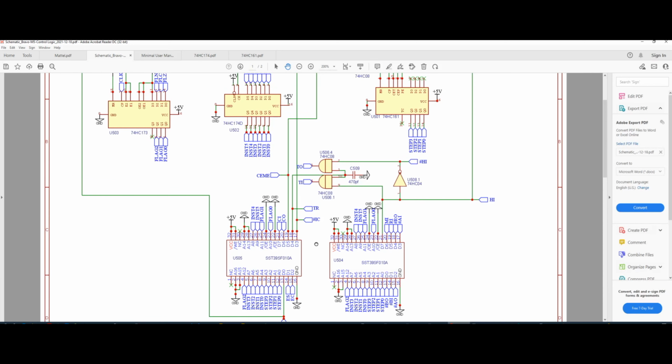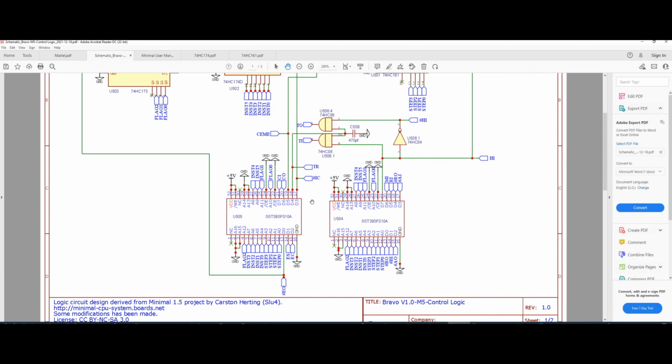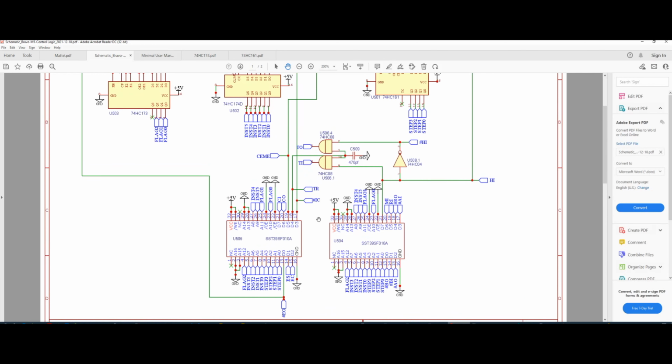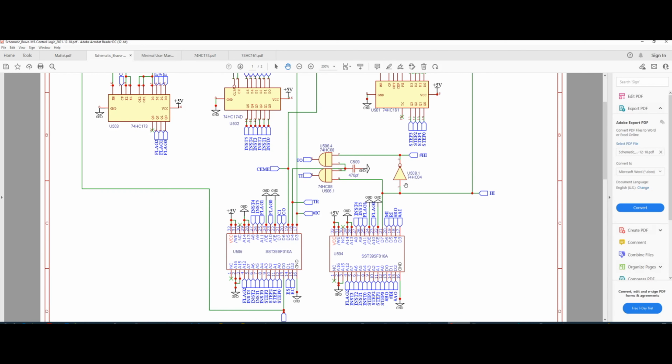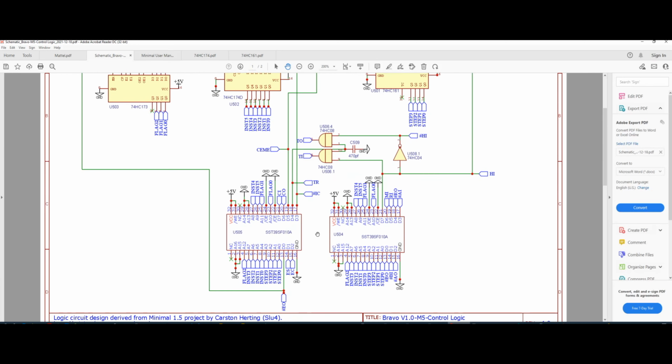Now, in regard to the control signals, let's have a look into more details here. So the input sides, again, are connected to both chips, identical. For example, step 0 pin here comes to A0 or address line 0 on both chips. And that means that we are addressing both chips at the same time, which is fine.